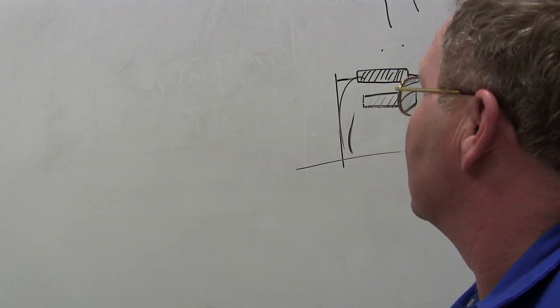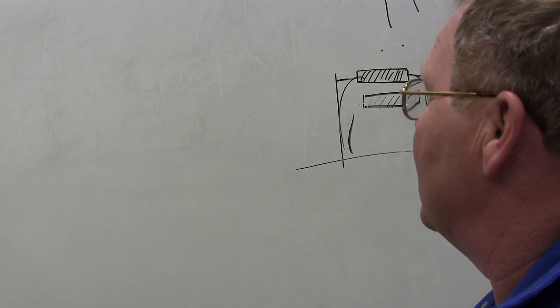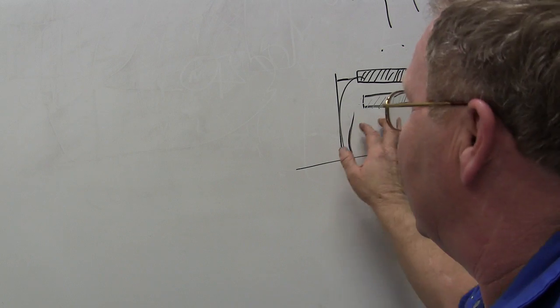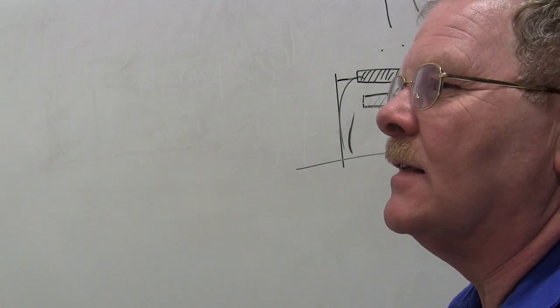And so as more air goes in, based on its comparison between that and that, it's measuring how much current it takes to keep that little platinum wire hot. Got that? That makes sense?